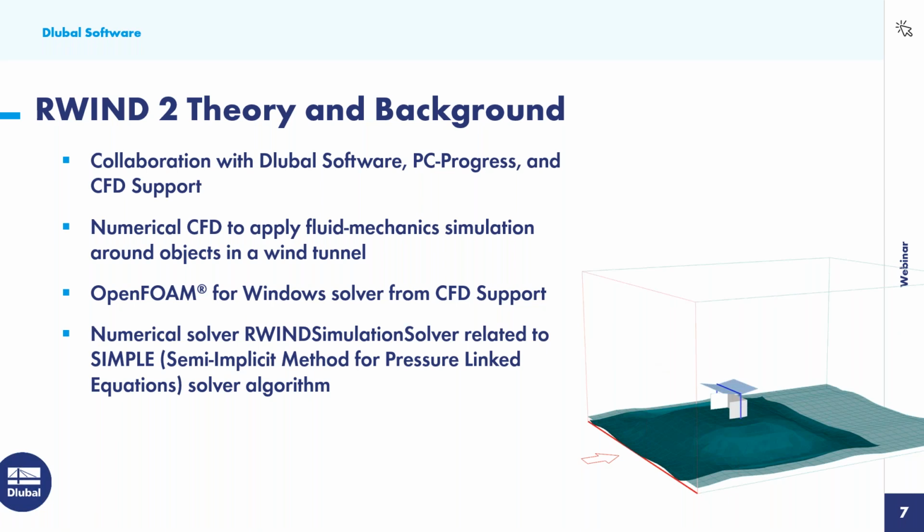It does utilize the OpenFOAM for Windows solver that was developed by CFD Support. It also utilizes the numerical solver RWIND Simulation solver, which is related to the SIMPLE solver algorithm, and SIMPLE stands for the semi-implicit method for pressure-linked equations.